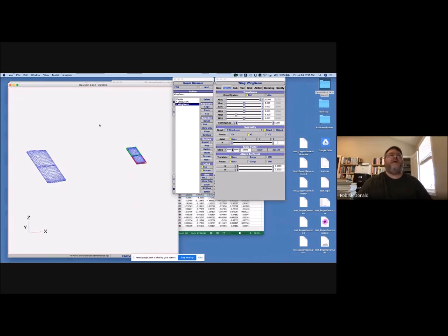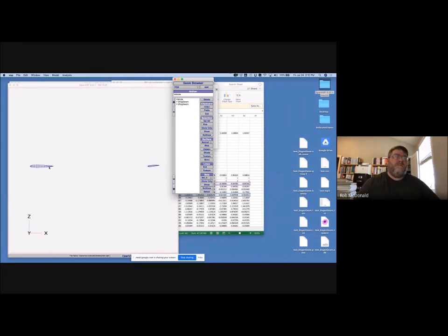So a normal airplane, right, with a wing and a tail, the main wing is set up to be lifting. Obviously, you need lift, but the horizontal tail is actually either downward cambered or at a negative angle relative to the wing, or is pointed down, or is an upside down camber, right? So it actually has a down lifting force, right? And so on a normal airplane, the tail is fighting against you, believe it or not.